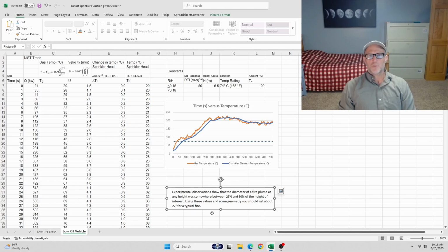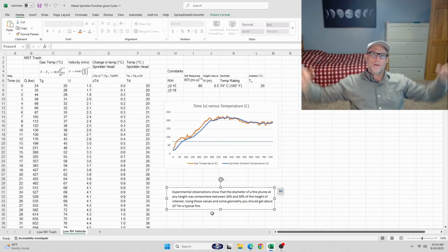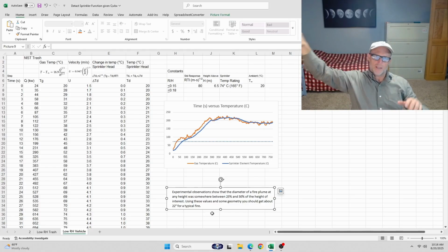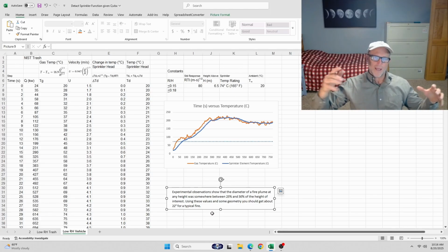The principle for sprinkler head activation is when those gases hit the ceiling, they go out in a horizontal format, and at some point they will hit a sprinkler head. Typically, just as an example, ordinary hazard protection, OH, you have different standards of protection in NFPA 13, but for OH, one head can protect no more than about 130 square feet.